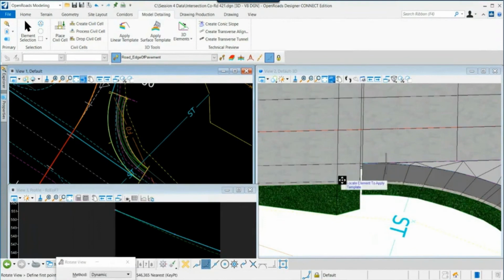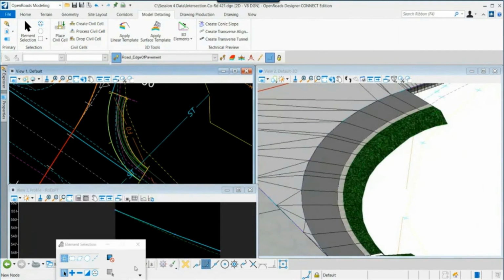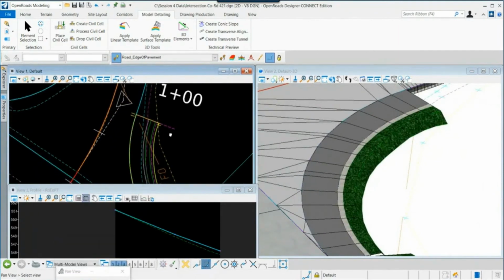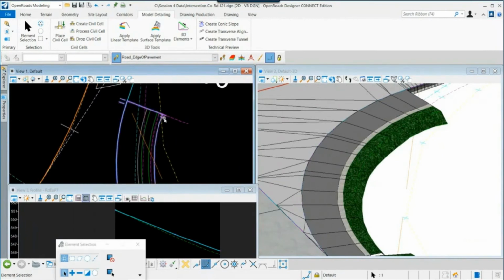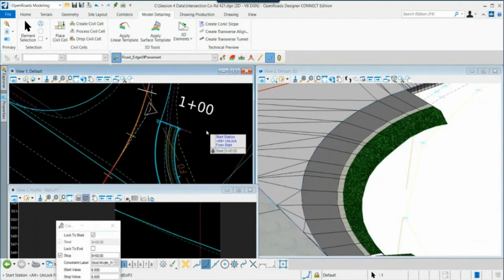But we can see now our shoulder's been placed, so that's great. Now, importantly here, if I want to taper that shoulder out, I can use parametric constraints. The width of this shoulder is definable outside the template. So I'm going to select the corridor, go here to parametric constraints. I want this to go from the beginning, of course, unto the end. So I'll push the Alt key, I'll data point, shoulder width right, that's the constraint label on that.